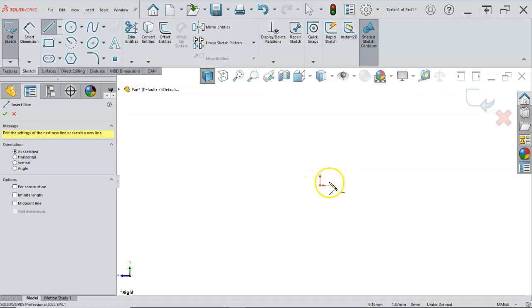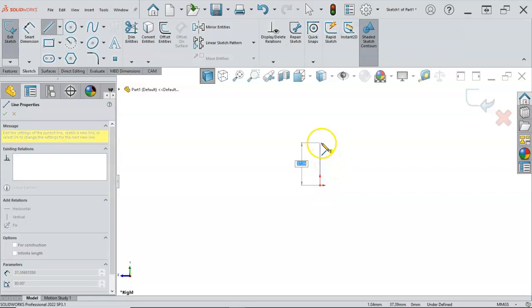Alright, so again, using that origin as my reference, long leg, short leg, I'm looking at it as I expect. Click, and we place it. This was the 40. Now this is going to bring off the next line. So 10, and it is in the horizontal because I have the yellow box with the horizontal. And down some distance, click.